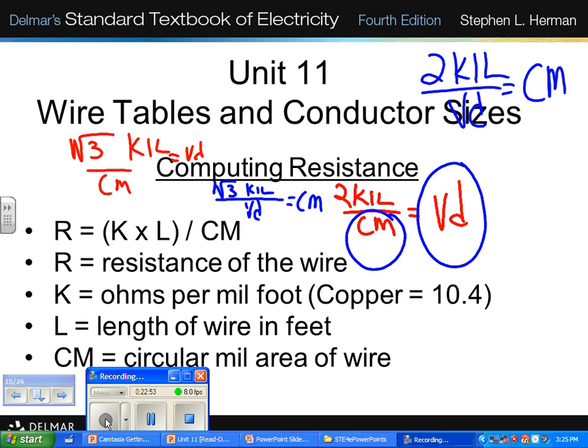3.6 volts is exactly correct. Now that number is going to keep coming up again and again, 3.6 volts. 120 volts is a very common service load voltage, and 3% is a very common voltage drop, so that number will keep coming up again and again. What's 5% of 120 volts? 6 volts even. So those numbers will come up again and again. Trust me on this. But the part you need to remember is 3%, 5%.